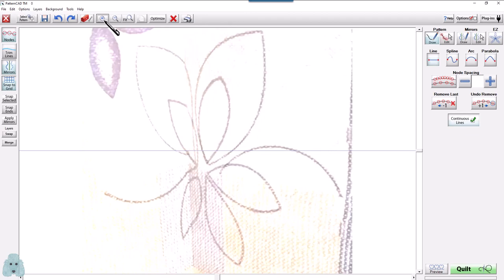So one thing I'm going to do is start my first point right here, so that for my design, I know it's going to begin on that plane, and then I will probably end it by adjusting my ending point here on the line. Let's start here. I also want to select splines. So now I'm no longer drawing a straight line. I'm going to draw a line with some curves. So I'm going to select spline in my draw. Off snap to grid. That will allow me to make a soft curvy line.